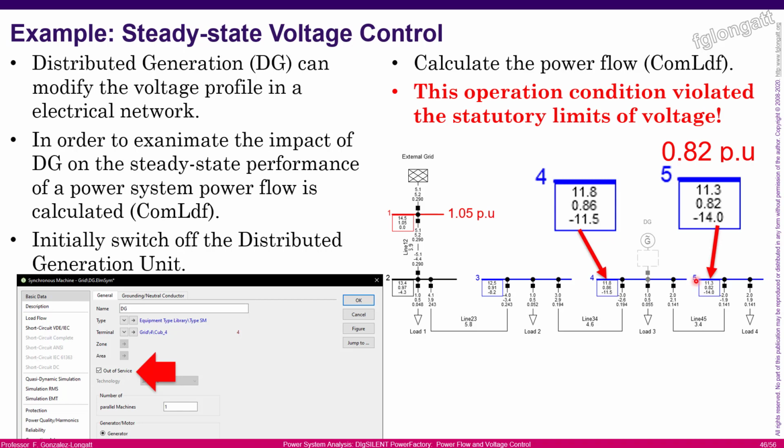Everyone must recognize that there is some legislation and some documents that say that the voltage that you receive at home, or the voltage that is provided by the company, must be inside a band. In some countries, the size of that band, the maximum and minimum voltage that is allowed inside the network in a steady-state condition, is defined in percentage. In some countries it could be 10%, others 8 or 5%, or even less, depending on the location, or even bigger. In some countries they allow even voltage drops larger than 10%. However, in this case, this is a very poor feeder with a very bad load profile. The idea here is to use this feeder to identify some measurements and some effects related with voltage control and voltage dependency.